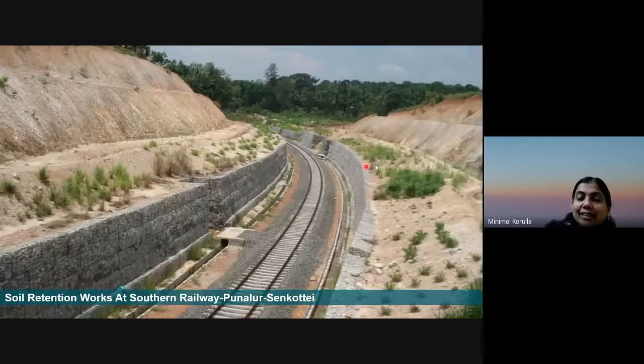This is again a structure for slope stability in Kerala. This is one of the first reinforced soil systems in this country. It is for Southern Railway, Trivandrum. We are seeing only the fascia, but a reinforced soil system, a steel mesh, is going inside the soil and reinforcing it. And the pore water pressure will be released through the porous gabions.